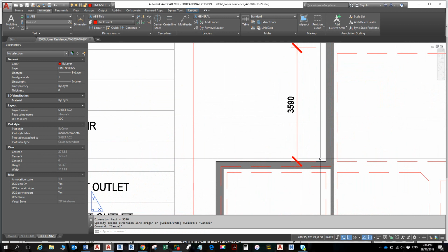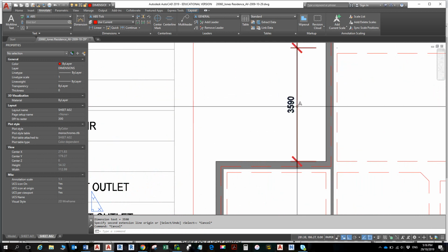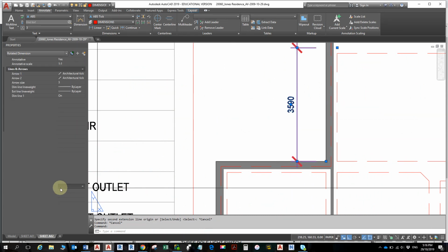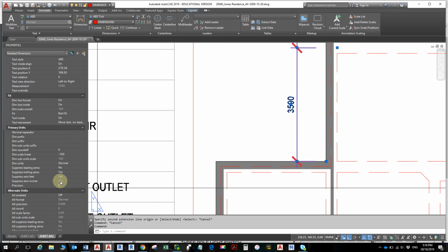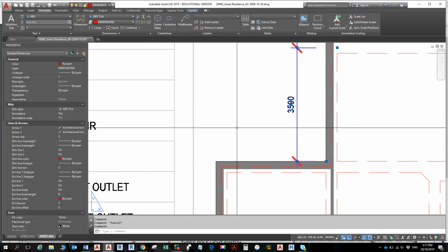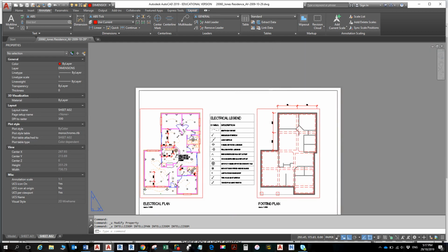So hopefully you're getting the dimensions. I have had issues before. If it doesn't quite lock in, you might get this one saying something like 3,590,000. In which case you need to click on here, go to your properties over here, and change that number to be 1, enter, and then it will change back to -100. It will normally say something like -1,000 or something like that. It might, I don't know. It didn't this time. Not sure where I am. But anyway, I will undo that. Unless it's broken, don't try and fix it. All right.